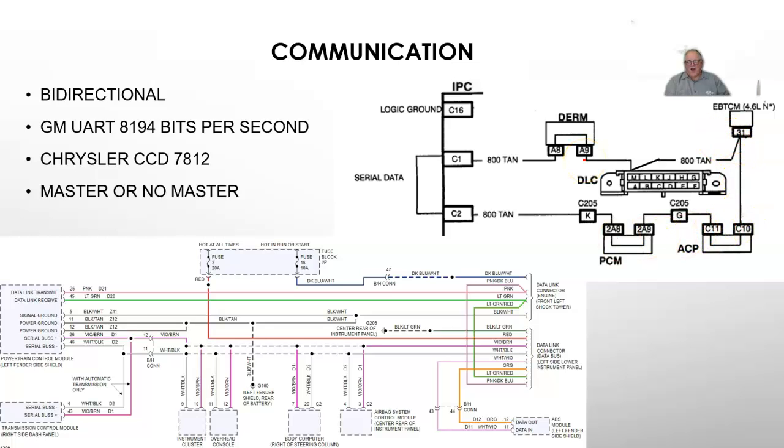This was considered high fault tolerance. If this wire broke right here, communication from here could go this direction, communication from this one could go that direction. With a single break in the wire on this system, you would never know the wire is broken, communication would happen no problem. Protocol for communication required a master and slave.